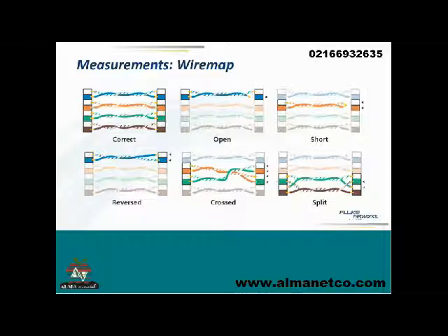And in a split pair, what you see happen is if you look at the ends, everything's connected to where it should be. In other words, if I follow the, say, that green one all the way through to the other end, even though it goes through the brown cable, it comes out to the green end on the other side. And you think, well, that should be okay. That's not okay, because what will happen is the transmit and receive pairs will be twisted together, say, for example, the positive transmit and receive pairs instead of the positive and negative. What happens is instead of the signals canceling out, as we showed in the earlier example, they'll actually be constantly together all along the length of the cable. The crosstalk will be tremendous, much more than if they were just straight, and the cable won't work. And once again, as I pointed out, sometimes these kinds of things will work for a while, or sometimes they'll have a lot of errors.